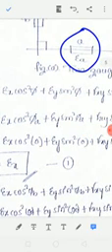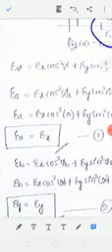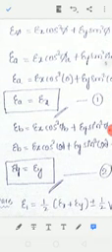Okay, now what you have to do, you substitute 0 degrees for phi A. Epsilon A is kept as usual. Now epsilon x cos square 0 degrees plus epsilon y sin square 0 degrees and gamma xy sin 0 degrees cos 0 degrees. So now we can simplify this one. You will get epsilon A equal to epsilon x. Can we take this as equation number 1? Okay. Now similarly, epsilon B is having angle phi B.